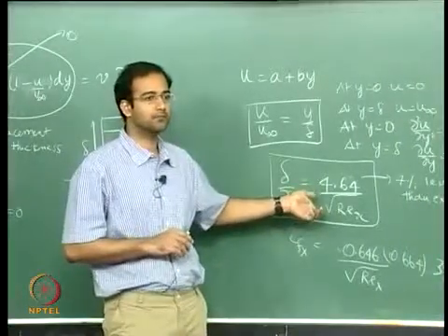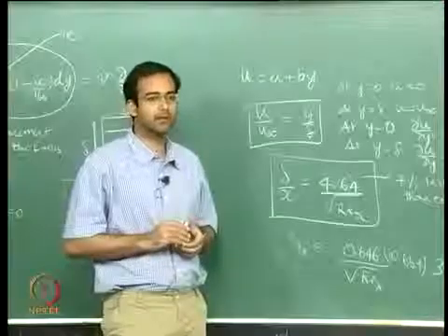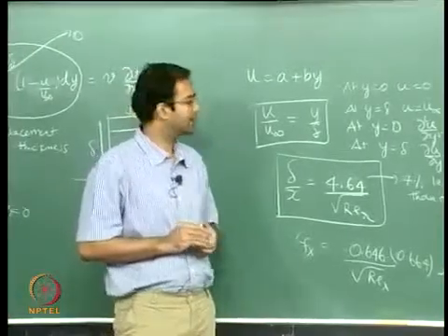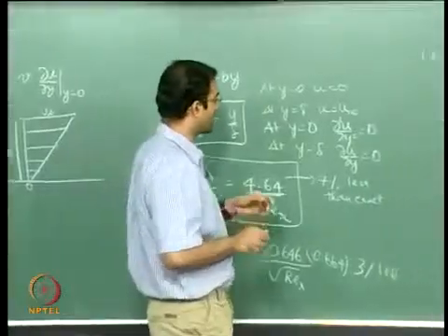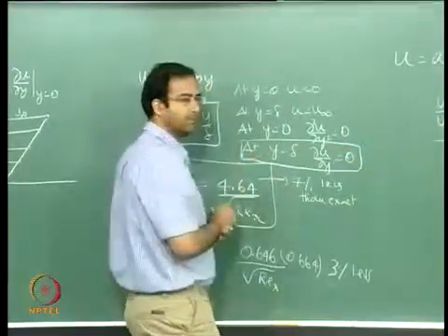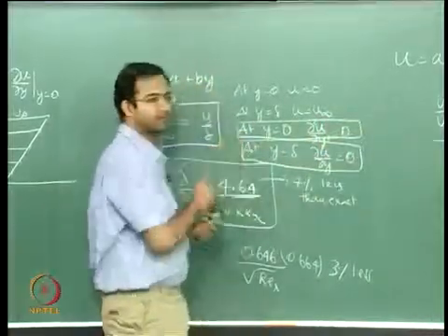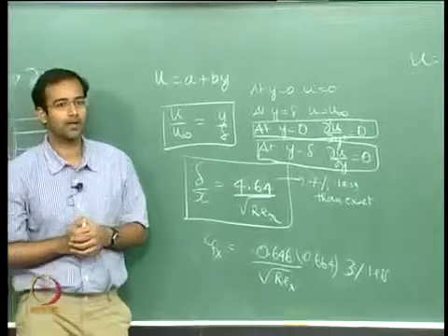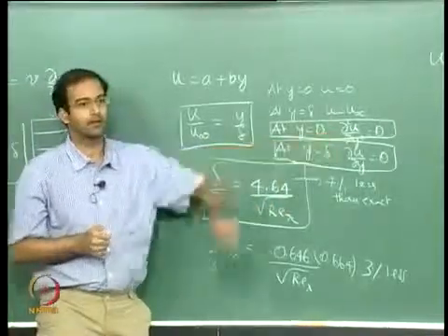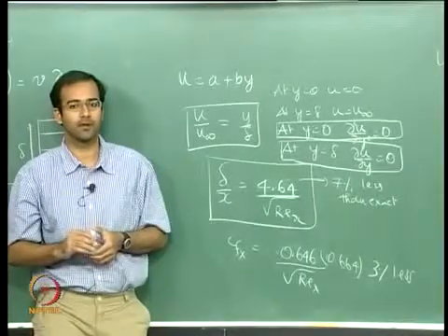In fact, using a quadratic polynomial will even deteriorate the solution. Okay, that is also because in the quadratic case you use this boundary condition at y equal to delta, rather than using that boundary condition, because you have only up to the quadratic term, you cannot take the derivative up to the second order, you have to take up to first order and apply it.